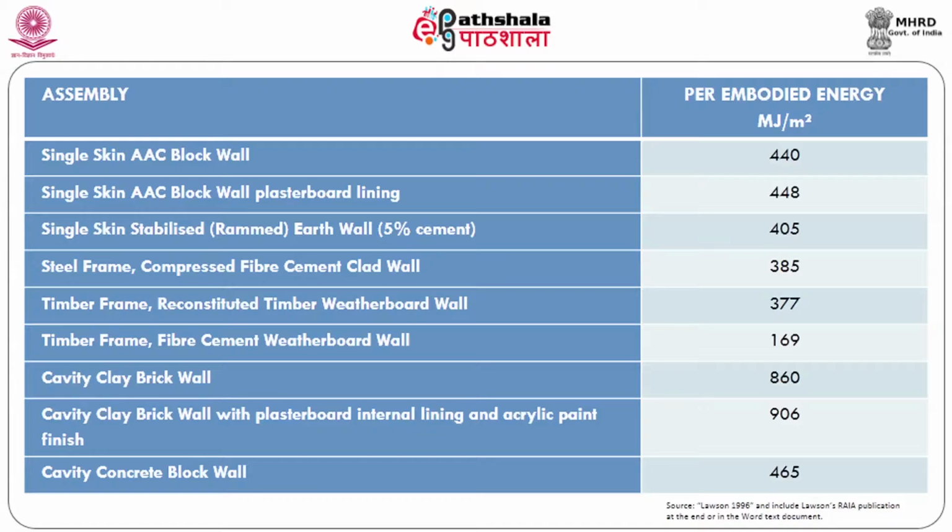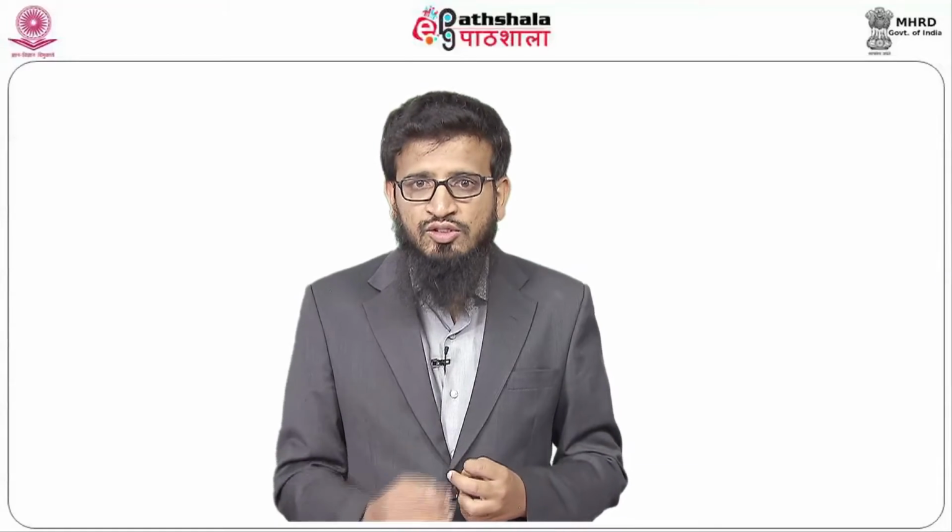So, it becomes very important to understand which one you need to use. The tables provided in this module are basically to give an understanding of how each component works and how each one has an impact on the total embodied energy of the building. So, while selecting a material while designing, you need to look at which one and why you are using it. Embodied energy is not the total picture of eco houses, it is also important how you recycle them. So, it is just a basic gist, the first initial step to make a sustainable, eco-friendly house.